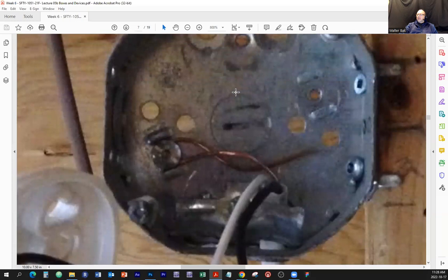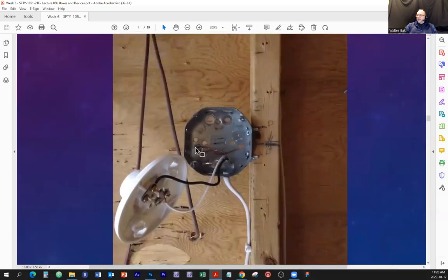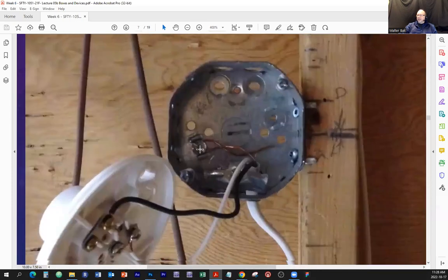Create a little bit of a zigzag maybe, and then put that into the bonding terminal, just so the wire has some sort of breathing space, breathing comfort in there. And if you need to service that, replace this, replace that, the other thing, you still have some wire to play with as far as length, so you don't get yourself cut off, and then you're going to have to make a pigtail, and that will be a second choice.